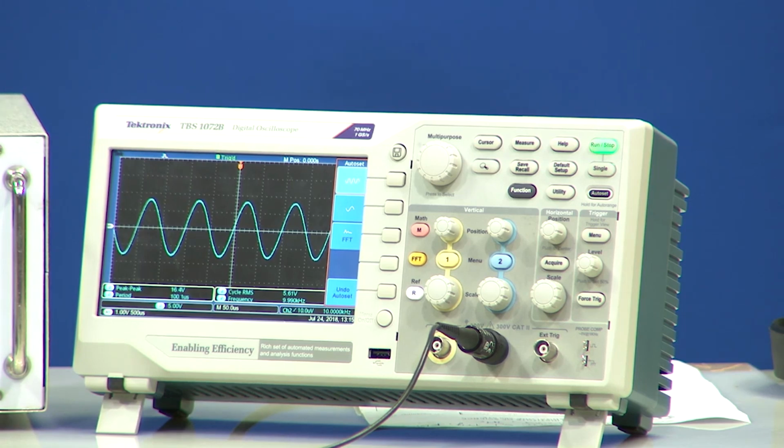So, around 12.5 volt input you should begin to see the saturation. So, when you begin to see the saturation, the input voltage will be 12.5 volt peak to peak. So, from 0 volt till 12.5 volt peak to peak, where saturation begins, or 0 to 6.25 volt sinusoidal wave, would be the range of the operational amplifier, correct.